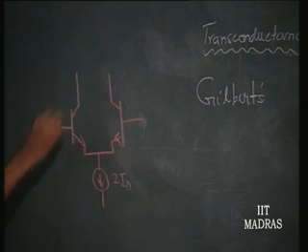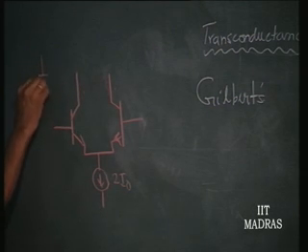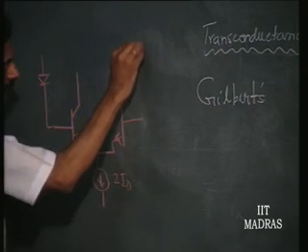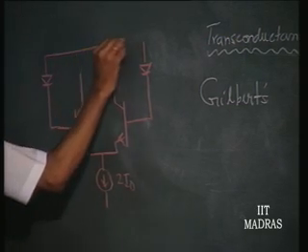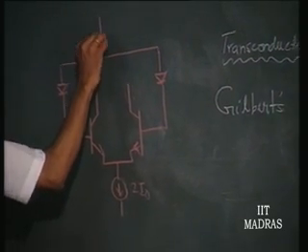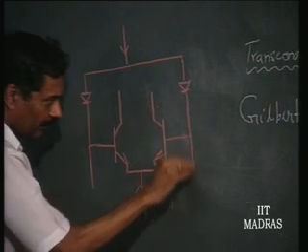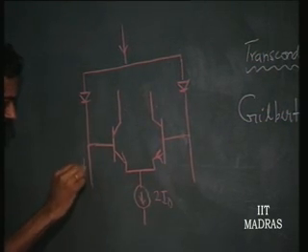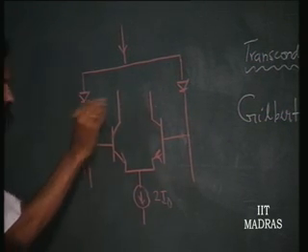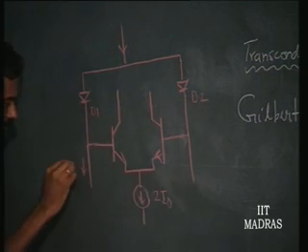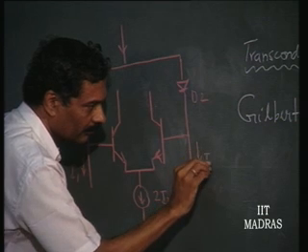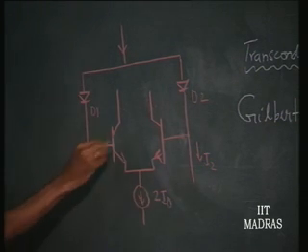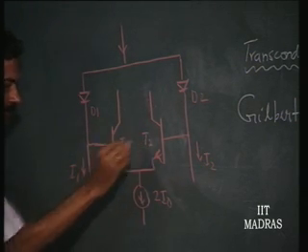Basically, we will have I naught and I naught flowing through this when these two are connected to ground, but let us say we have 2 diodes connected to this, which are forward biased, such that the input currents to these diodes D 1 and D 2 are respectively I 1 and I 2. Then these are T 1 and T 2 transistors.